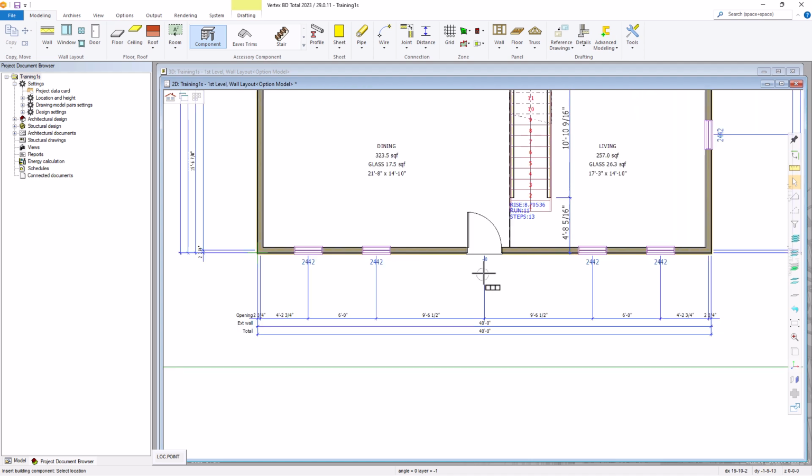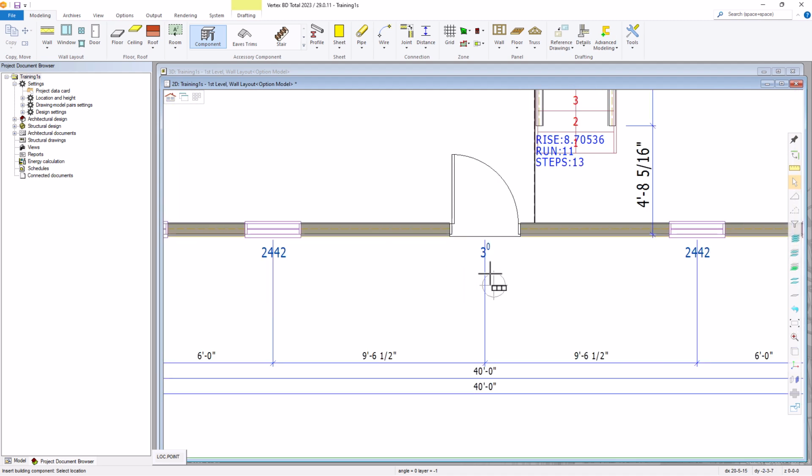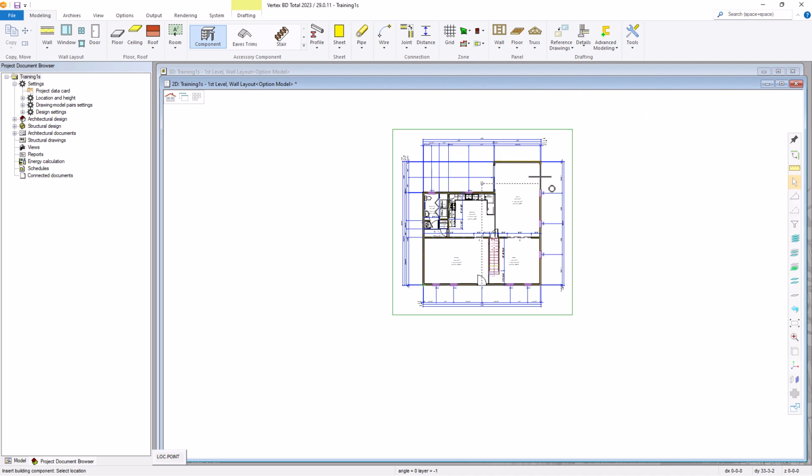So that door is centered horizontally, so we'll just hit Q off this point and use that as a reference. So we'll hit the letter Q and lock it in a vertical. And now we need to find the midpoint between that corner and this corner so that it places it in the center vertically.